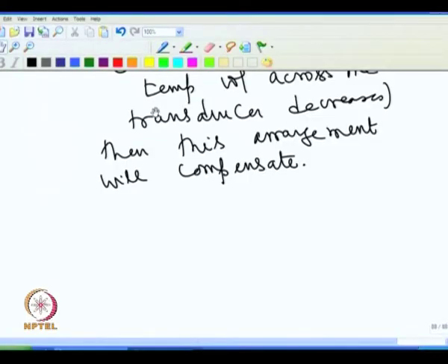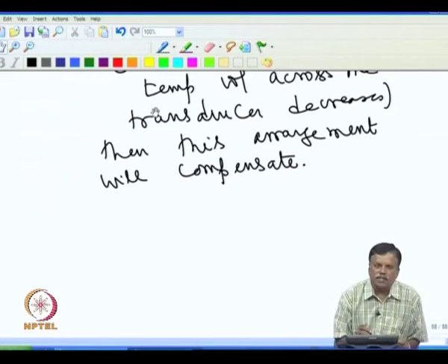So, in this case the transistor drift is used for our advantage, and this kind of application is common in the real world, because the transistor is a very dependable temperature drift element, as the base emitter voltage changes accurately 2.2 millivolt per degree C. This can be utilized at many places, because this kind of accuracy you will not get in a thermistor and so on.